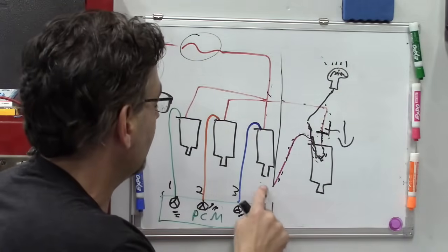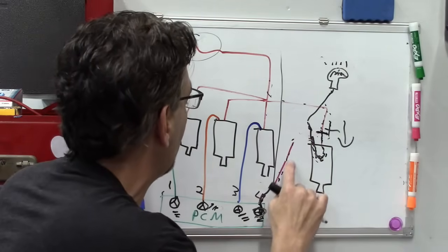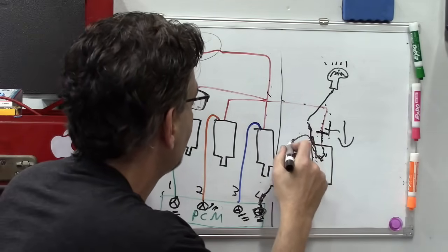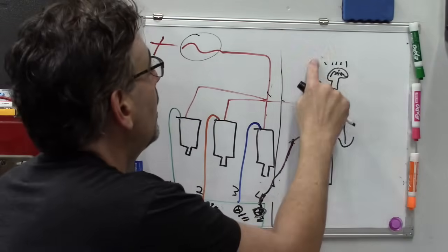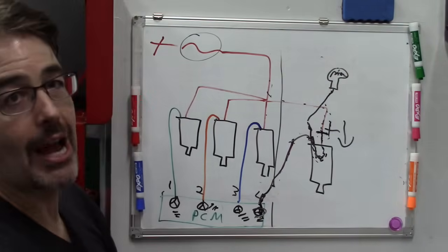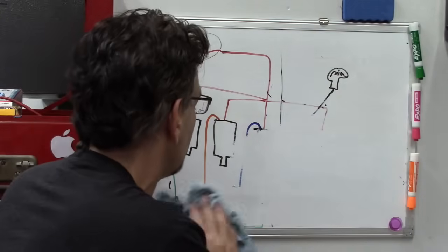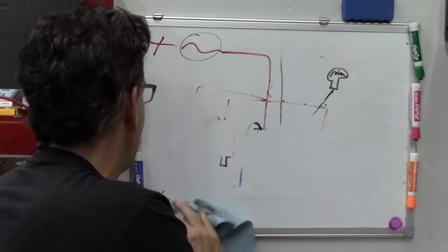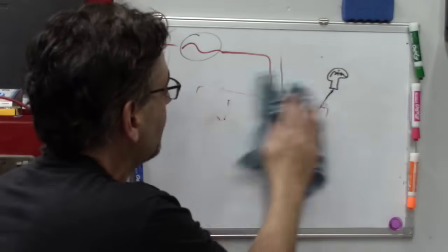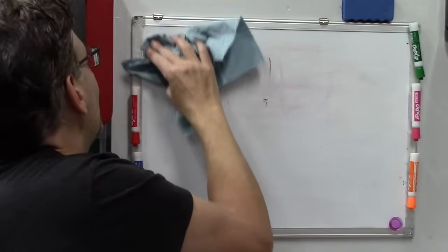PCM says, okay, let's complete the ground. It completes the ground again. We lose our power on this line through voltage drop. I'm tapped into where there's voltage drop, the light goes out. So hopefully that makes sense to you and you are comfortable being able to test a system like that and identify whether it's ground side or positive side controlled just by looking at it sometimes.